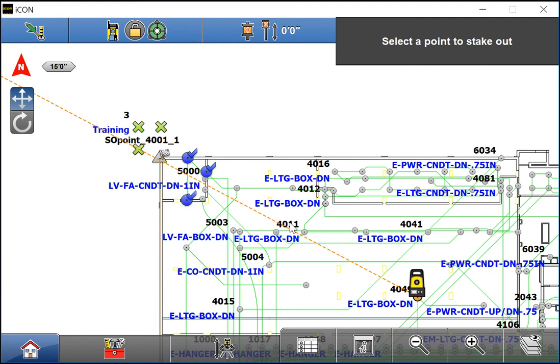On your normal tablet, this would complete the file export. You can navigate to the data folder on your tablet's file explorer and see the file. Attach the file to an email and send it back to your CAD tech. They can import your points to the original CAD drawing and generate as-built reports or perform quality control checks with this information. This is very useful when you find yourself in a situation where the GC is saying something was laid out incorrectly. This is your digital record of the work you performed, and your safety net should you run into problems.